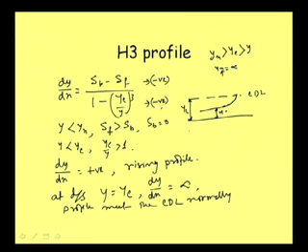Well, then at upstream y approximately equal to 0, this will become infinity, so that way this becomes undefined. So, we should not go to that point, and for practical purpose the profile is undefined.